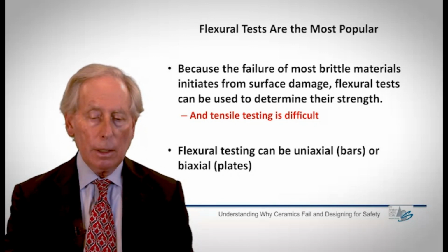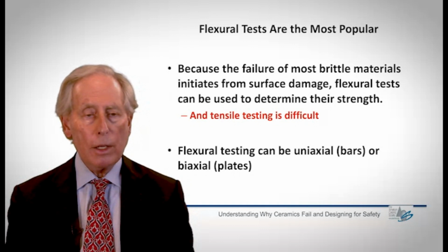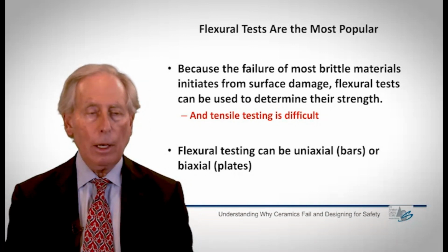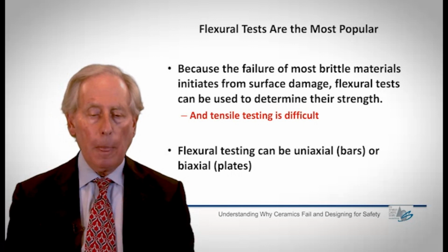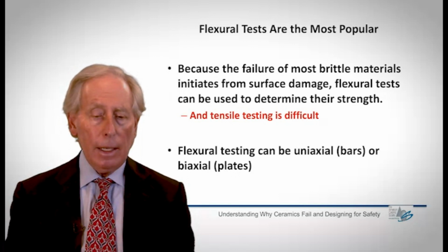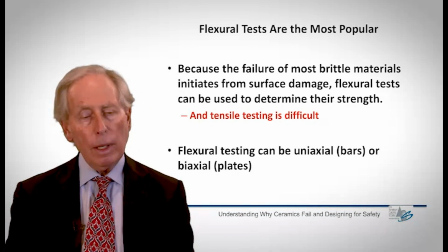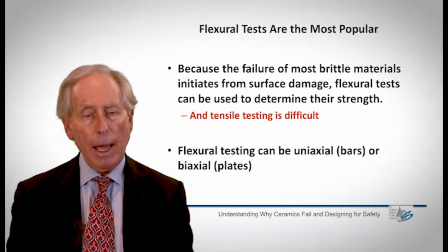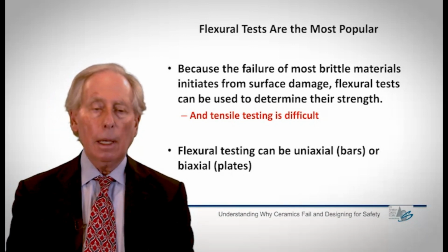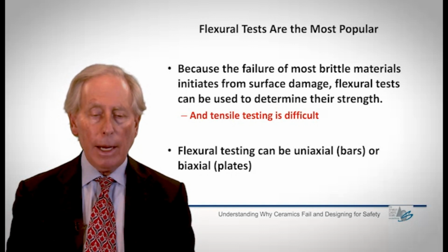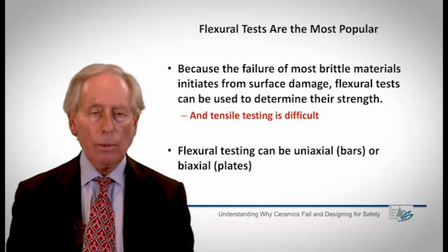Flexural testing can be conducted either uniaxially on bars of material or biaxially on plates or discs of material. Either way, one of the key points, and I'll make it again later, is that for any of these, if I want to really see how the component is going to behave, the flexural test specimens must be prepared in exactly the same way as the final finish on the component.